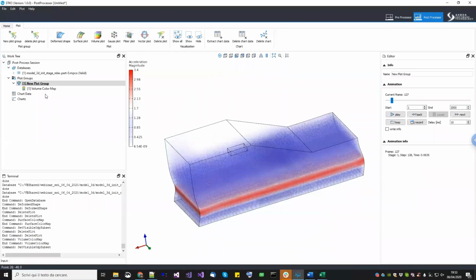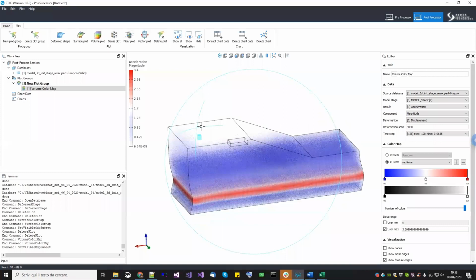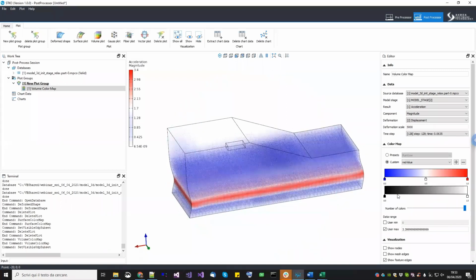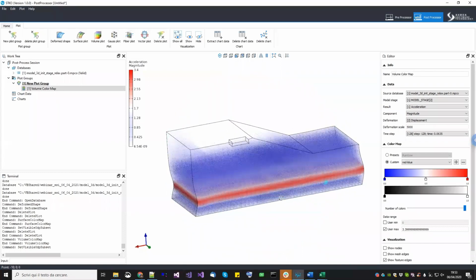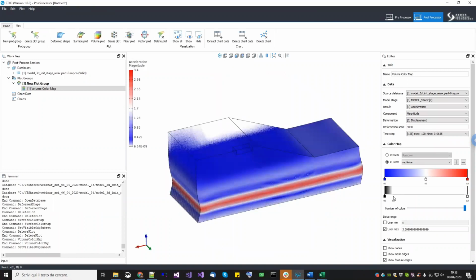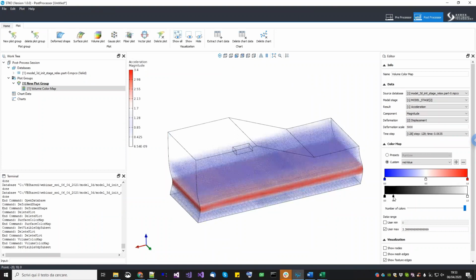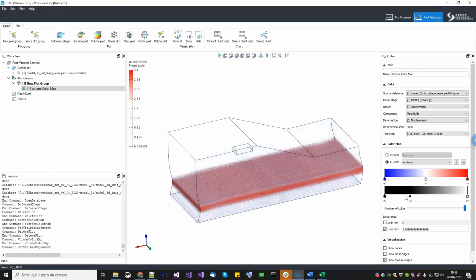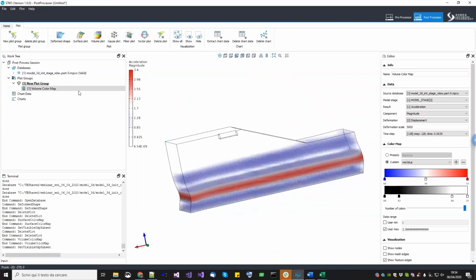And now, of course, when you're doing volume plots, you can play with the transparency map. Black is mapped to the minimum value and means completely transparent. White means completely visible. Inside, it is interpolated. Now, let's say we want to make this division between visible and not visible even sharper. So we can create another point here and make it black. If you want to increase the non-visible part, we can just drag it through the white like this. In the same way, we can create another white point here and bring it like this. So you can play with those values and look at what's going on inside.